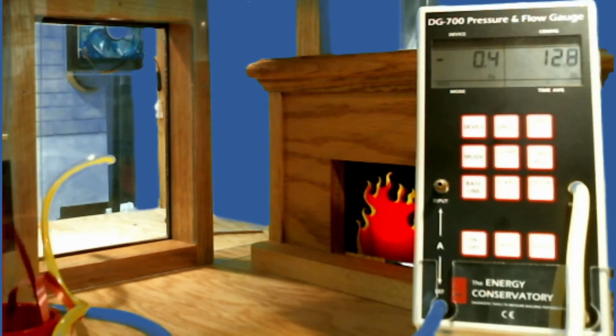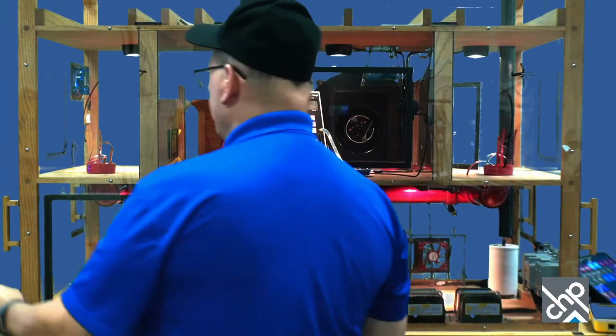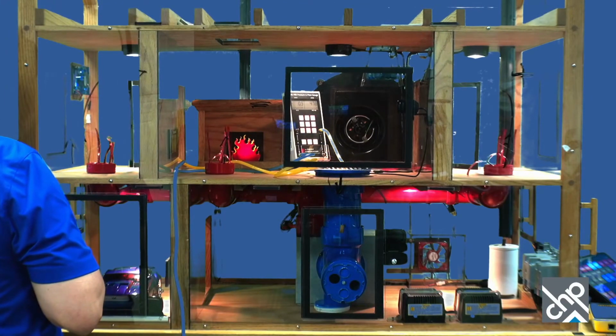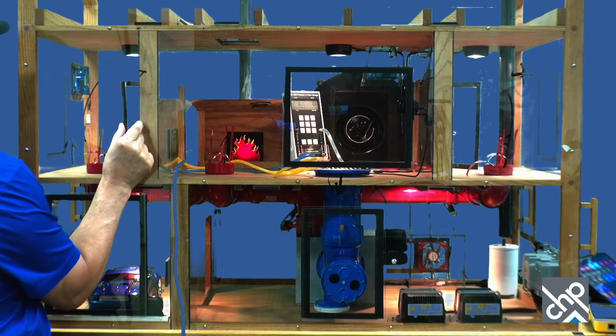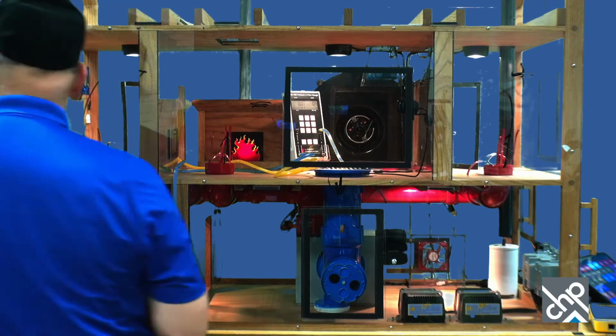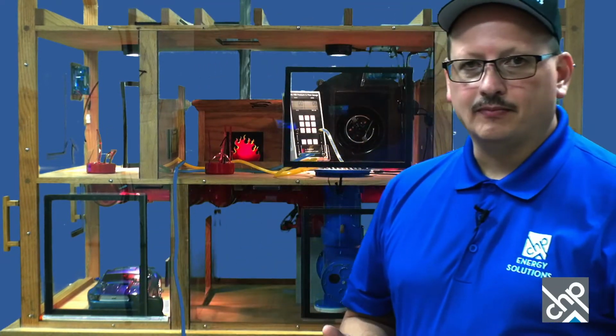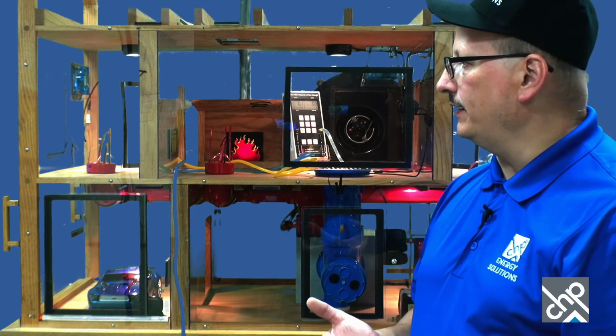And what you want to do is, when you open that door, let's see if it'll show up here. When the door is open there, you're actually measuring the gap of how far you had the door open. And then there's a little table that we'll use sometimes. So you measure the gap of the door, and depending on how big the door is, you can figure out the net free area.